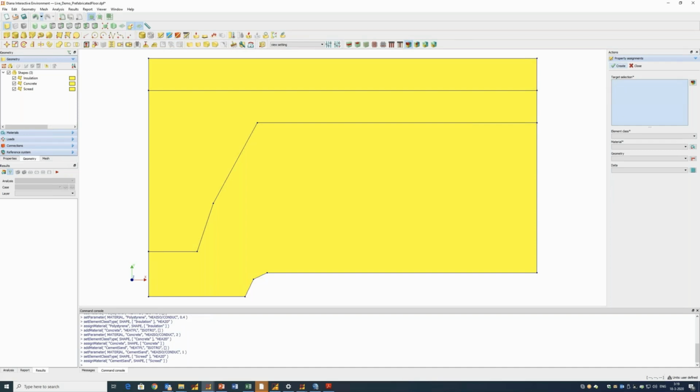We are now going to move to the boundary condition, which is actually one of the key points of this example of today. And it will illustrate what I have been explaining about the boundary condition in my short presentation. So first I will start with the boundary condition at the bottom, along this edge where we have a temperature of 10 degrees. So I'm going to define a thermal boundary condition.